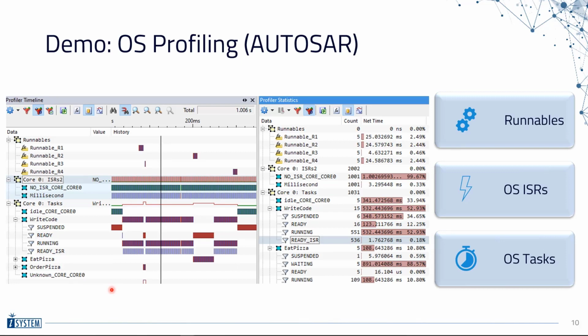As the first step, we are looking at the operating system. Also from a technical point of view, it does make sense looking at the OS first, because measuring specific timing parameters also on functions does require that the profile is aware of the OS context switches.